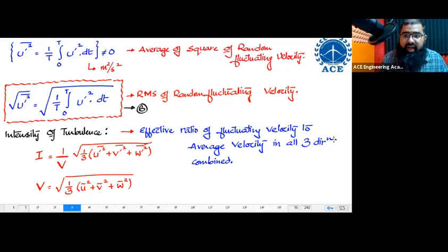It is regarding the analysis of a single fluid particle whenever it is under a turbulent flow regime. That fluid particle is going to have three significant values. One value is its time average velocity. That is in the previous slide. You have taken that down. The second value is the fluctuating velocities average, RMS of fluctuating velocity, which you are seeing over here.